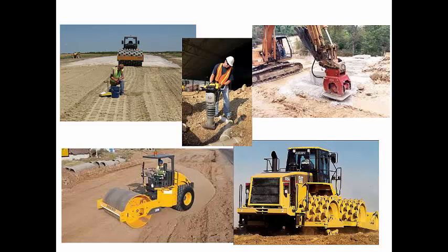You can see in the upper left that a technician is performing a density test on the soil to compare to the laboratory results using a nuclear density gauge. There are also opportunities when backfill around pipe, backfill around manholes, other trenching activities must be performed, and backfill of that becomes very critical. Lower right is just an overlap gradient. It's a big Cat 825, which is a large, heavy sheep's foot roller with a blade on the front.